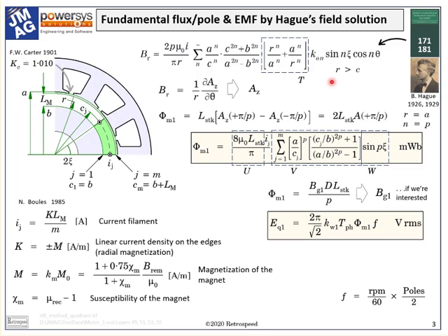We can see Haig's solution here reproduced from the Green Book. A and B define the outer and inner boundaries of the solution domain, and the iron is assumed to be infinitely permeable. It has to be said that this is a serious limitation of Haig's method, and a strong reason to use the finite element method in general, although the error in this particular example will be quite small. Many other authors have developed field solutions of this type, notably Howe and Zhu at Sheffield University.